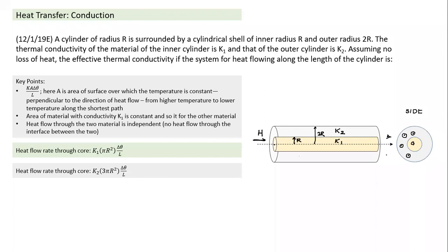So in this case, both rods have the same temperature difference, similar to resistances having the same potential difference. Here also the rods are connected across an identical temperature difference. They are in parallel. If they are in parallel, as we say, the current is equal to the sum of the currents through independent resistors. Here the heat flow rate is the sum, H1 plus H2. I can independently calculate H1 and H2.